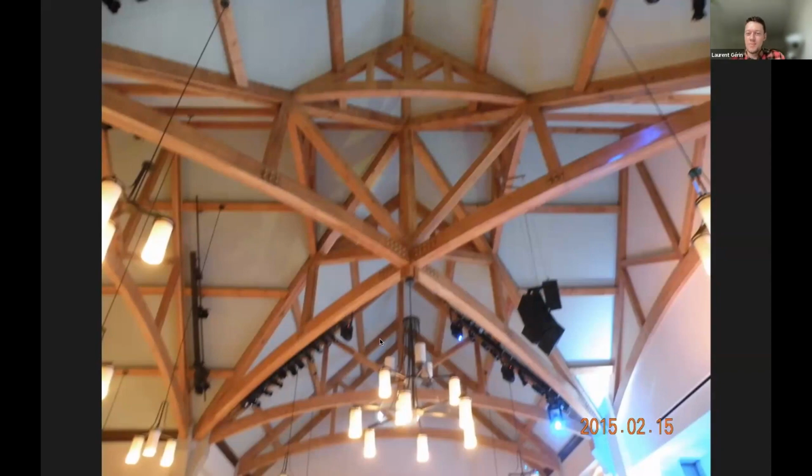We've got a question here from Gio. Could the base of the steeple be a truss as well, or would that just screw things up? Yeah, I don't see where that would be any advantage, particularly. Those walls of the steeple were like shear walls as far as wind loading is concerned, which, by the way, put an interesting twist on the analysis, because that wind load had to be generated into this frame.